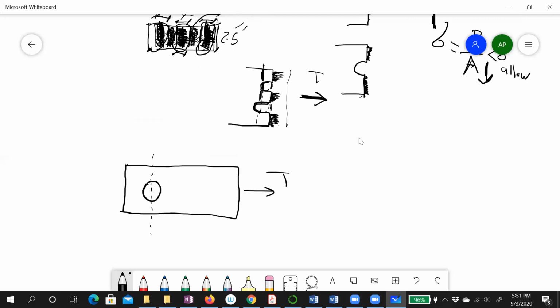For the shear, once we apply the force here, the shear happens in these regions. These regions are very critical regions. Why? Because this hole is very close to this edge, right?